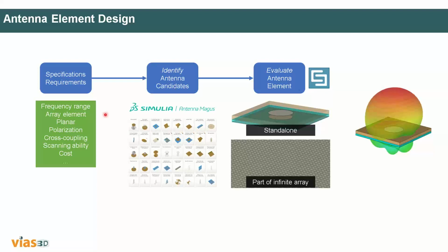Sequential excitation is one of the favorable types of excitation used in industry, where you are exciting every port one at a time. And simultaneous excitation is where you apply excitation to all the ports at the same time. We also developed one method for any structure running on a frequency domain method, called DDM, domain decomposition. I will also show you how the performance varies.